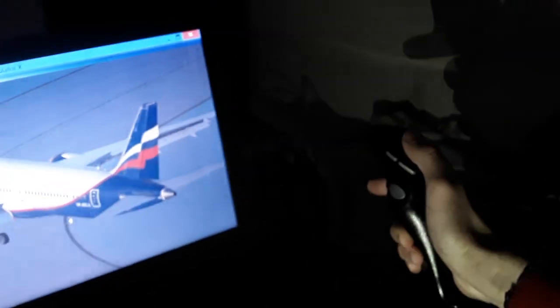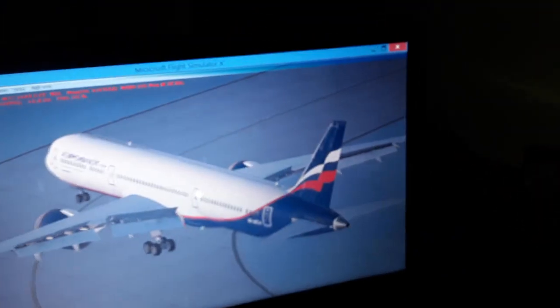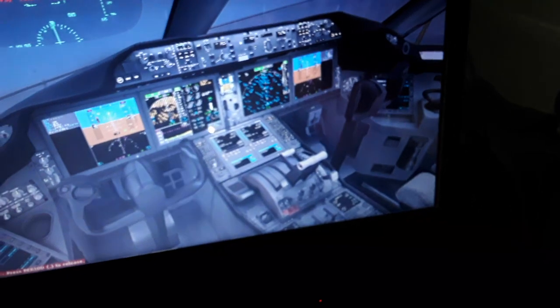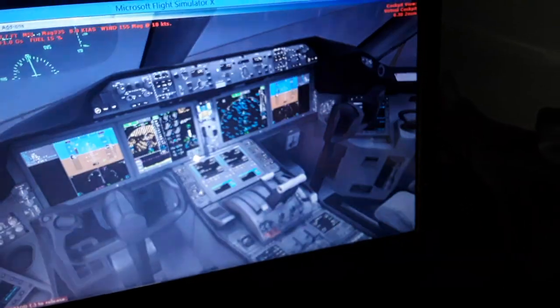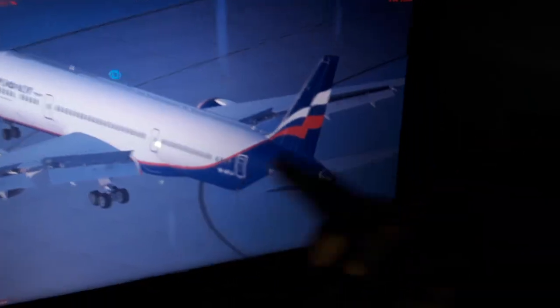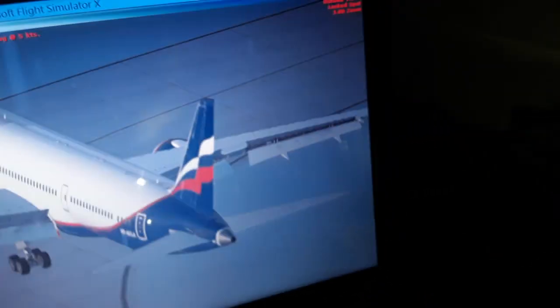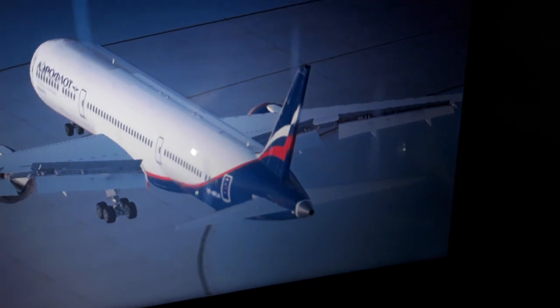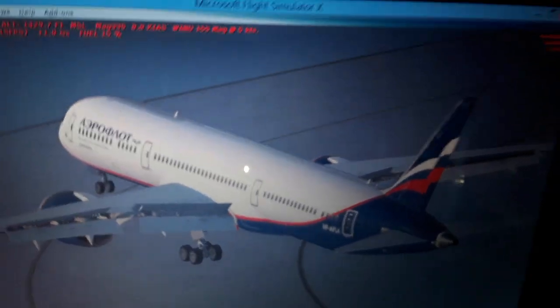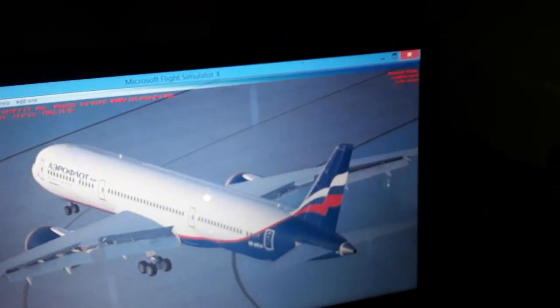And we do the vice versa for landing. It's all automatic from the computers. You don't need to do anything. Just use your rudder pedals to steer the aircraft for takeoff and for landing. Also in the air you have only the rudder. So after takeoff you have the rudder to make left and right turns like this, doing balance and maneuvers, the vertical stabilizer and rudder.